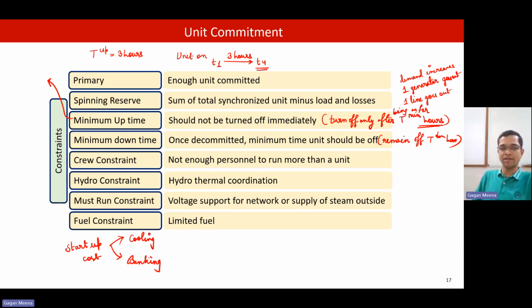And this is more costly. It also depends on the duration for which it is off. Cooling means the unit is completely cooled down and then brought back, while banking means it is not completely cooled down. It was just shut off a few hours back, and a minimum operating temperature is still maintained.